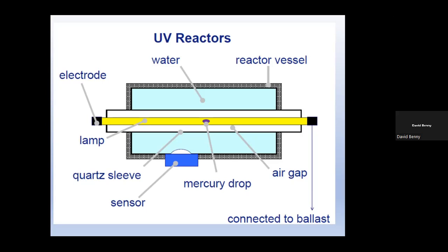At the Beetham wastewater treatment plant, where we have UV, we have a modulating weir on the outfall. Based on the flow levels coming in, ultrasonic controls modulate this weir so you can raise or lower it so that you have a constant flow of water through the chamber.